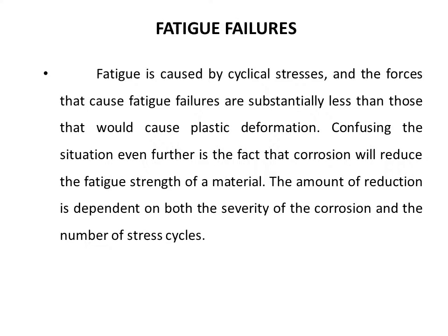Fatigue failures. Fatigue is caused by cyclical stresses, and the forces that cause fatigue failures are substantially less than those that would cause plastic deformation. Confusing the situation even further is the fact that corrosion will reduce the fatigue strength of a material.